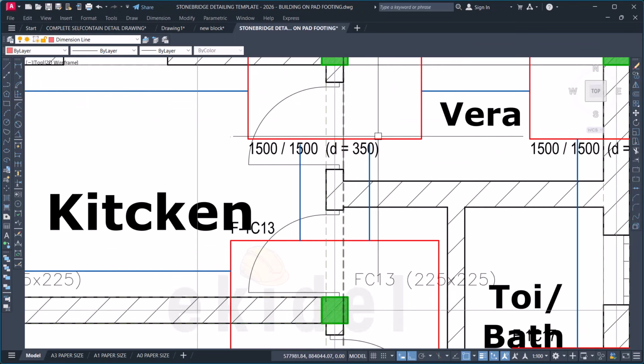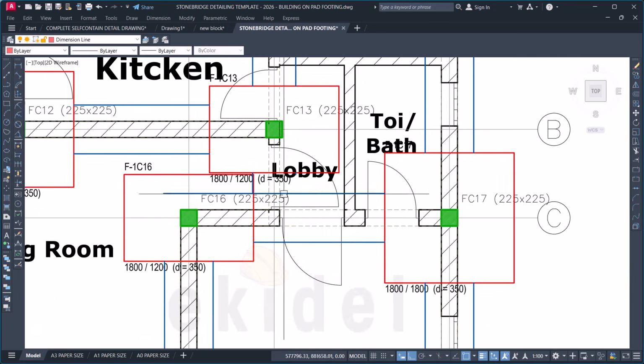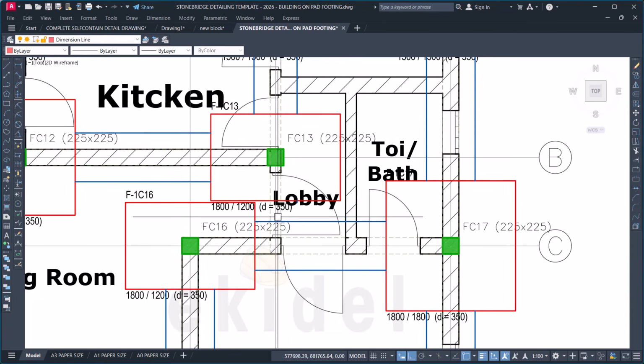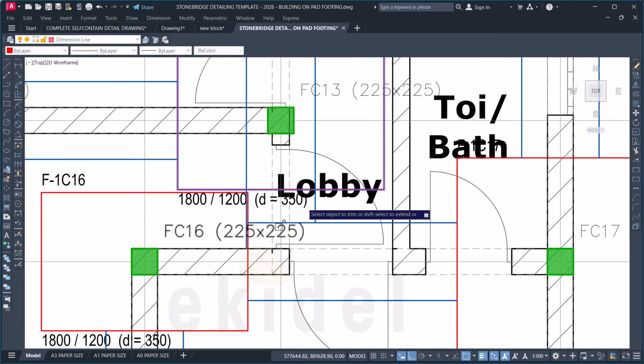So with this now, I can then come here. Everything looks fine. Click on this first, extend this line. So make sure all your trench line is touching the footing base. Okay, that's fine. And again, I will come here, click on this, click on this, and then I will come now, hold this, EX enter, and extend this. And this will not go, so to extend, you can choose to click on this and then extend this just to have where it will fall. Then we can now hold this and then trim off any trenches that pass through this place, take it off. That's fine.